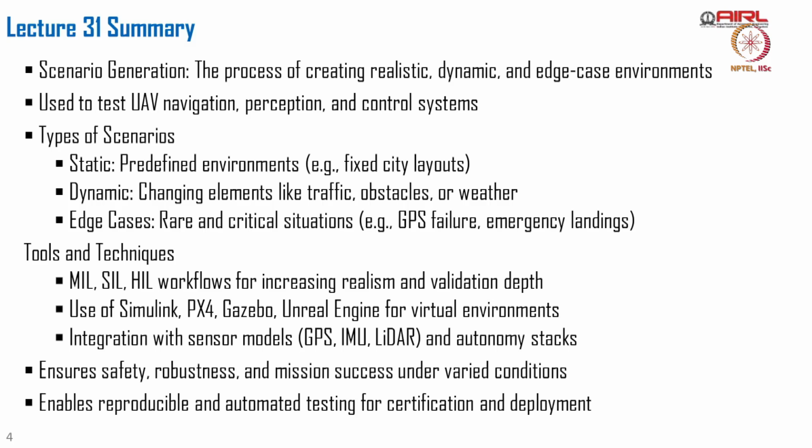The performance of the algorithm can be validated and visualized very nicely. One can use Simulink itself, or Gazebo, or the Unreal environment to visualize the virtual environments. You can nicely integrate with sensor modules like GPS, IMU, LiDAR, camera, so that you can easily verify different autonomous stacks using the scenario generator.